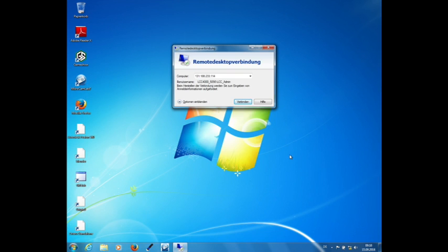So if you do something like that, the way to go is to switch off the ion getter pump, open the gate valve to the buffer chamber, and have the turbo pump pump off all the crap that's in there. Then after the weekend, you close the buffer, close the main gate valve again, and switch on the ion getter pump again.